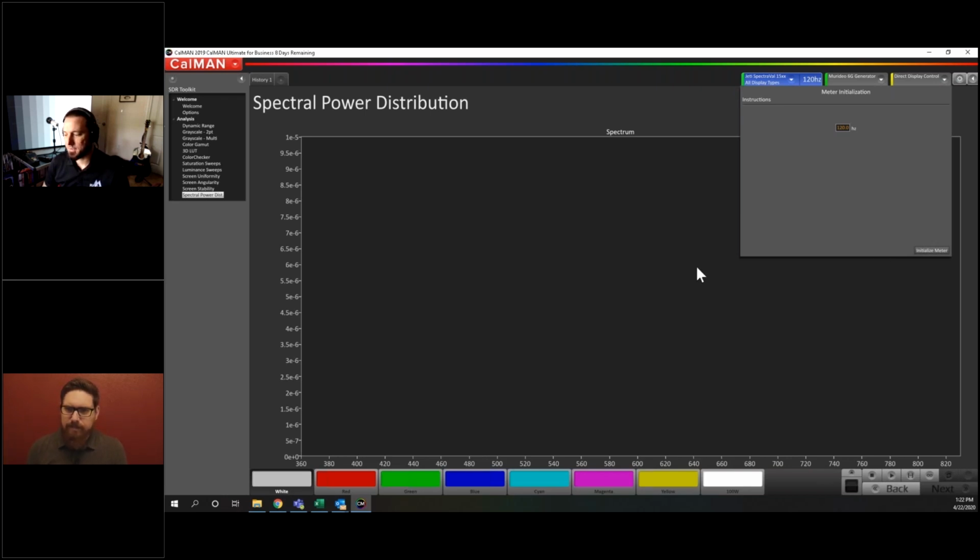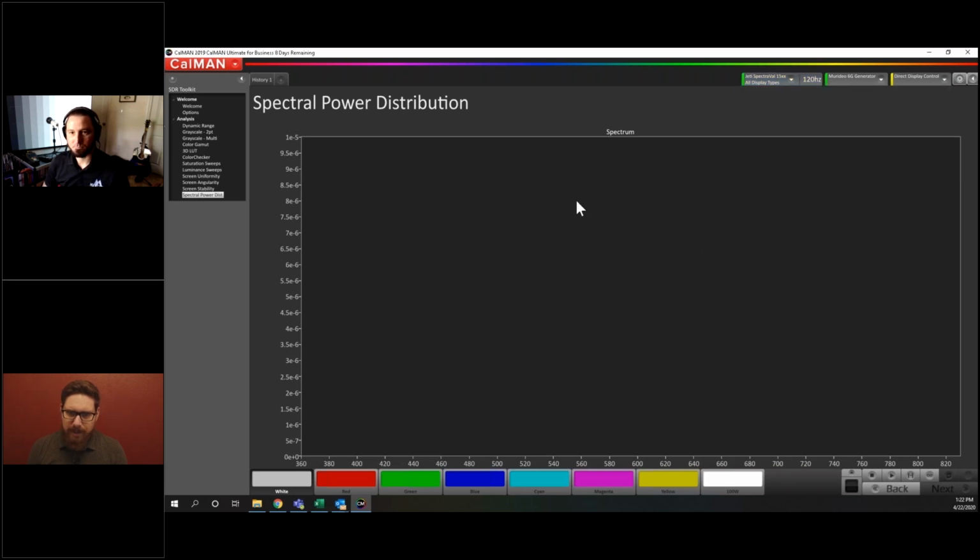What's the major use case for doing this part of it? The syncing that you just did. Certain meters, to be most accurate, need to essentially read data in the same cadence as the display is refreshing, so it's not trying to read between the refreshes. It's kind of like a camera syncing up with 60 hertz lights. If it's set up to a wrong frequency, then you get a flashing.